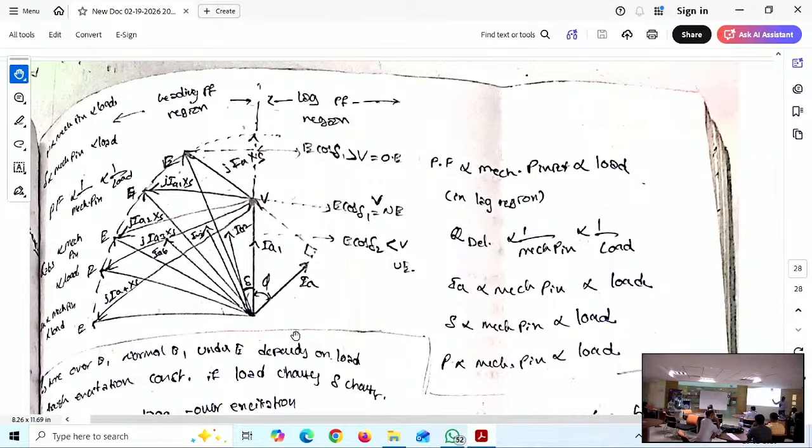So that is the method to make them understand without looking at the circuit diagram. They keep the circuit in mind, draw it themselves, and finally we as faculty go there and check which side the positive terminal is connected to, which meter is connected, whether the voltmeter is connected across or in series, per phase. If you are connecting the no load test and the short circuit test for alternators, we will see whether the terminals are open and whether voltage is connected line to line. So this should come with a flow. That experimental analysis we are going to see based on this understanding.